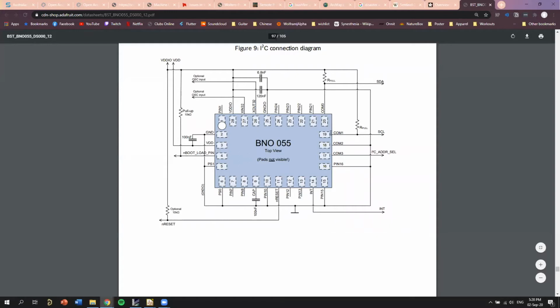Then if we put a 0 here, this resistor is going to ensure that we have 3.3 volts here, and then 0 volts here, and it kind of just completes the circuit, or it ensures that this actually is low with reference to our power supply. And normally our pull-up resistors are a pretty big value.